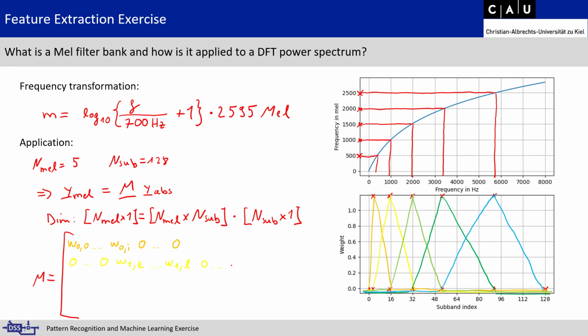And that's the same for the other two subbands that follow, and then for the last subband, I start with zeros, and then at some index R, I have non-zero elements, and I go up to coefficient 128, which is of course index number 127. And our very last index could be 0 or non-zero depending on how you end your triangle there, but we don't fill it up with zeros back there because this is our last subband.